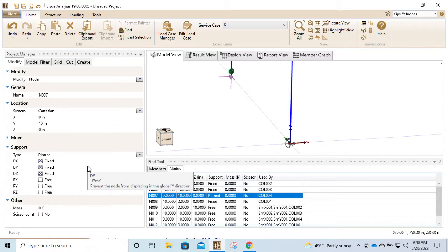And if we don't have it connected to an element, which is what we're saying there, we're saying that the line element that's connected is not allowing force to be transferred, then it's going to allow this node to spin, right? Because it cannot keep it from rotating, because we're saying that this line element that we're connected to has no fixity with respect to rotations.